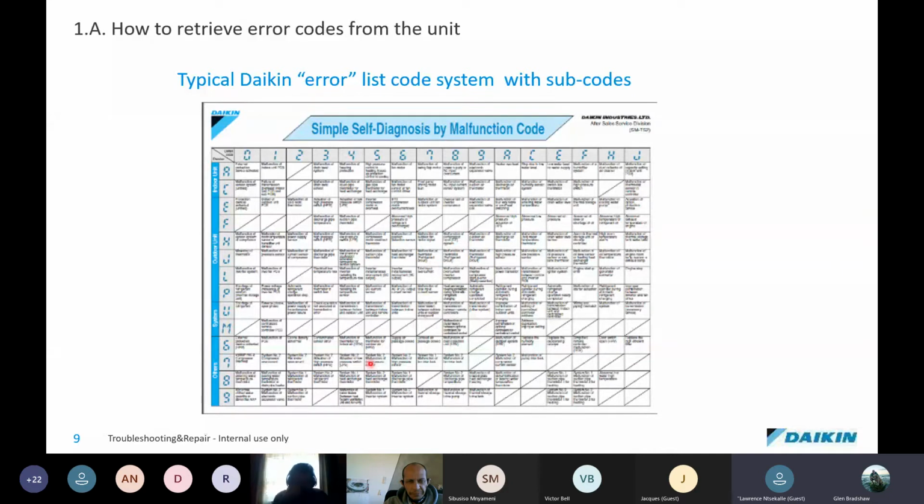The errors down the bottom here don't pertain to the equipment that we're talking about today. So generally, if you see errors A and C, you will know that you'll be heading towards the indoor unit to start your diagnosis. System errors can be intercommunication between the devices and the units, so there you may be moving around between indoor and outdoor.